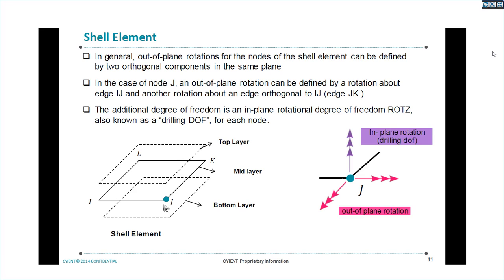We also have rotation. Okay. So this information is given to the program: the thickness h, and this element has additional degrees of freedom, rotations. These rotations and translations at the mid surface, along with the thickness, these three things will give the results at the top and bottom surface. This is simple math. Okay. This into height will give this value, as you are aware. Okay. So that is the main advantage of shell elements.